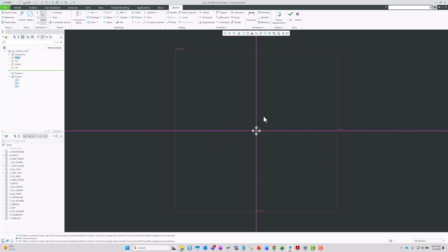For example, you can create a line here, starting in the first quadrant, and you will see that it automatically snaps to the same distance. If you don't have the center lines, let me remove this, you won't be able to snap because there is no reference to center it. That is why it's important to create them this way.